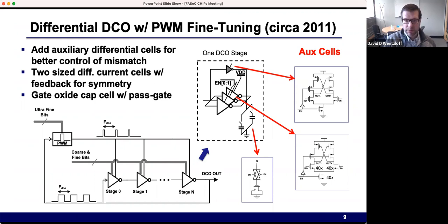And actually, this is the first cell-based PLL that we used in a radio. I think we did a 400 megahertz med radio, a binary network, W-band radio with this. But this is the first time that we used a ring oscillator that was automatically generated for a radio, meaning the phase noise performance is good enough for radio. So, all right, that's PWM. That's kind of an aside.